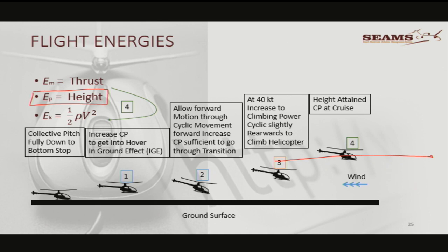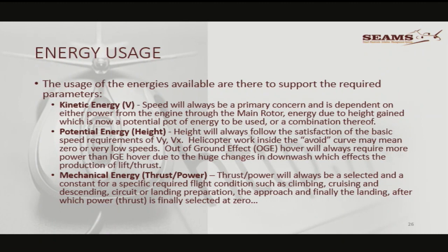And now if there's any excess thrust left, and you put, let's call it normal cruising power, then the speed will increase and the energy now only goes there, until the aircraft has reached its maximum cruising speed for the amount of energy available. But now it's level. It's already got its height. So that's just normal cruise.